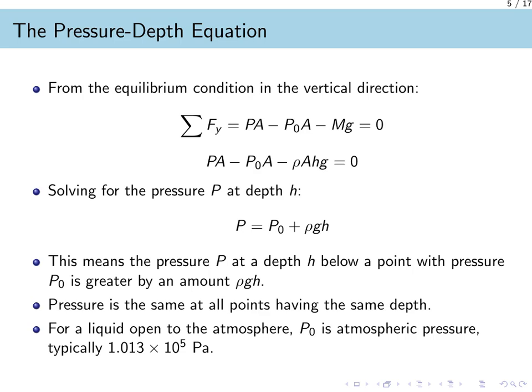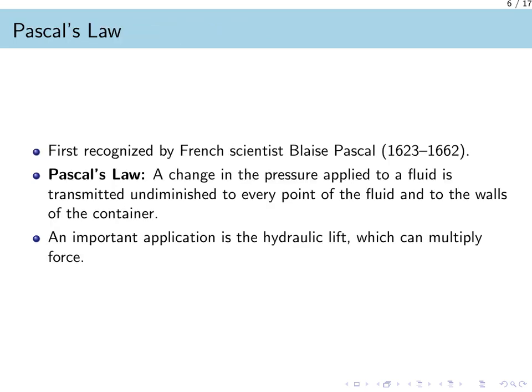This slide introduces a fundamental principle of fluid statics known as Pascal's law, which explains how we can use fluids to multiply force. The law states that a change in the pressure applied to an enclosed fluid is transmitted undiminished to every point within that fluid and to the walls of the container. It is important to note that this applies to the change in pressure, not the absolute pressure, which still increases with depth.